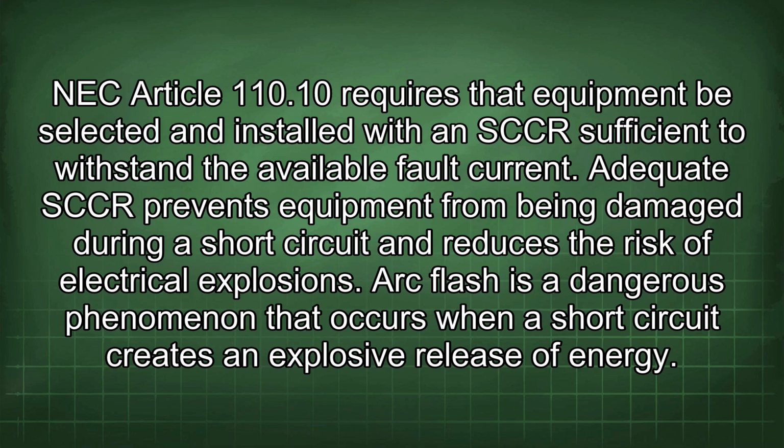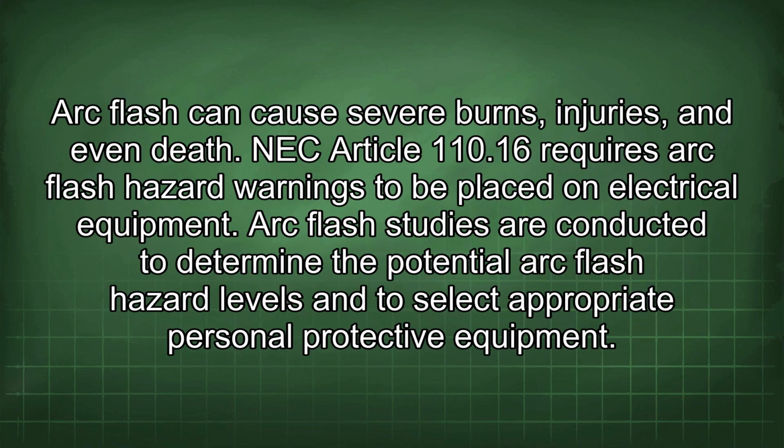Arc flash is a dangerous phenomenon that occurs when a short circuit creates an explosive release of energy. Arc flash can cause severe burns, injuries, and even death. NEC Article 110.16 requires arc flash hazard warnings to be placed on electrical equipment. Arc flash studies are conducted to determine the potential arc flash hazard levels and to select appropriate personal protective equipment.